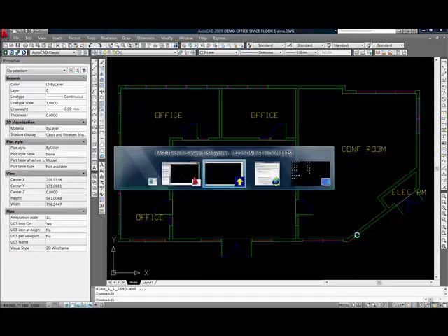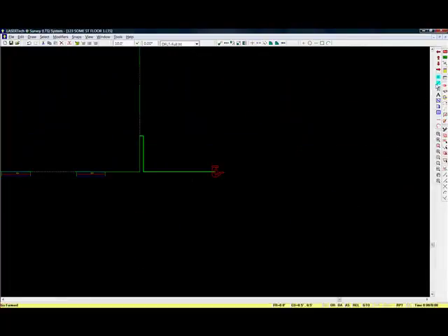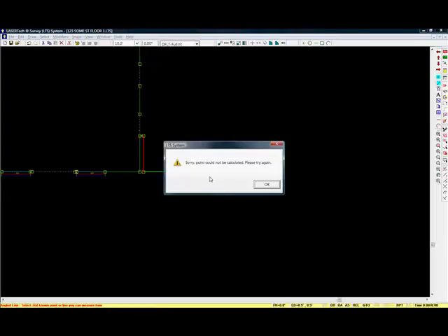So what we want to do is we tell the system we're going to lay out an angled line, and it says pick the first known point or line you can measure from. So we're going to measure from where we are standing, measure the length of that actual angled wall, and we're going to say it's 10 feet. Now we have to tell the system, okay, we have to take a measurement from some other point or line in our system, in our survey. So we're going to measure from this wall. We're just going to measure the offset, and we'll disto it and say it's 18 feet.